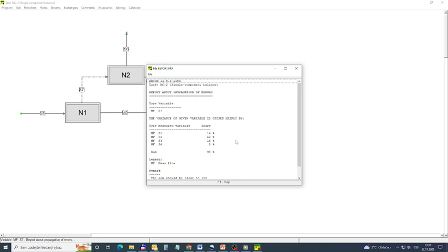In the column Share we find the main causes of flow rate S7 variance, which is a measure of its uncertainty. This says that 16% of the variance is caused by the uncertainty of flow rate S1, 62% by uncertainty of flow rate S2, etc. This informs us that the flow rate S2 is the bottleneck of S7 precision.